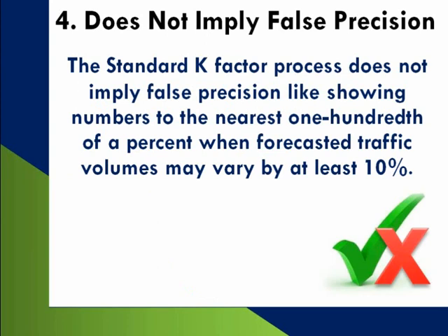And I kind of like this one. If you're familiar with K factors, we say 8.23%. And we think that's 1/100th of 1% we're saying we're using here, where traffic volumes vary by 10% and historically use this false precision. So 9%, we're rounding off to the nearest 0.5%.